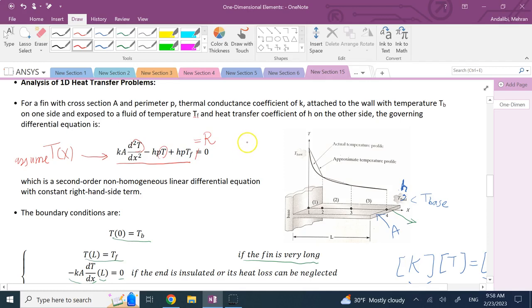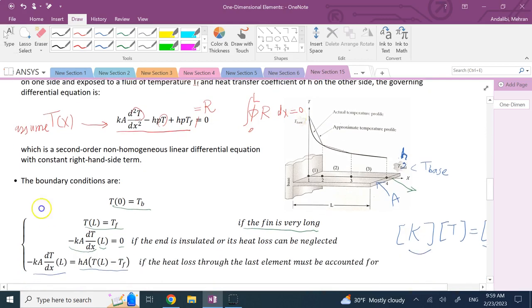And then we integrate that residual term multiplied by the functions phi, where the phi's are the members of that assumed solution. We multiply them by those and integrate over the whole domain and set it equal to 0. Just watch one of my previous videos called formulation methods in FEA. So that's the essence of Galerkin's method. So here we do the same thing.